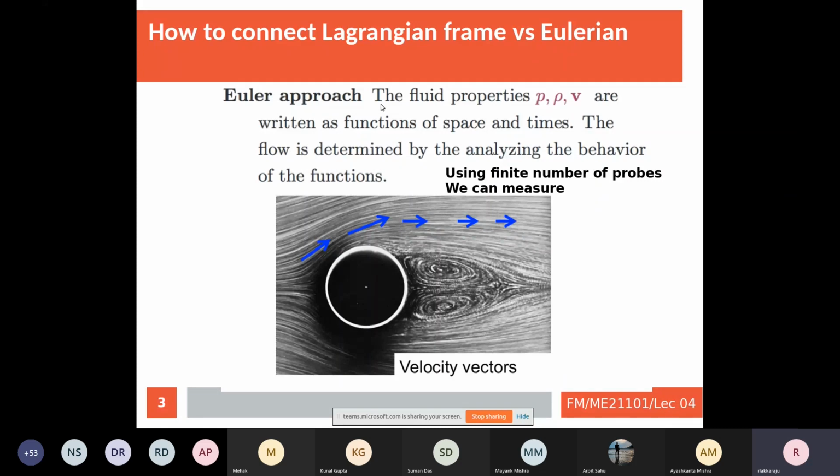No, Raja, that's not the better way. Maybe you sprinkle particles, aluminum kind of particles, mica particles, or colored particles. You shoot lasers. It reflects back. You calibrate it in a sophisticated way. You know with what velocity that aluminum particle is traversing.